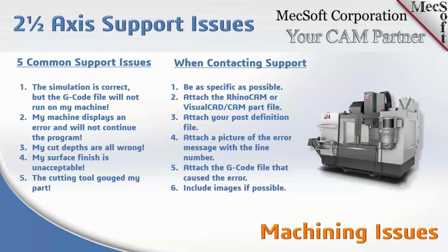Don, I've got a pet peeve that I have to talk about. Okay. Many times customers call in suddenly saying, "Hey, my part is coming out all wrong. Everything was working great until yesterday, and something changed suddenly. The software is not working like yesterday." If this happens, please note that if the software worked correctly yesterday, it's not going to change today. The problem most probably is with your machine. Something has changed on the machine. Maybe your machine has gone out of alignment, or maybe the part was not fixtured correctly.